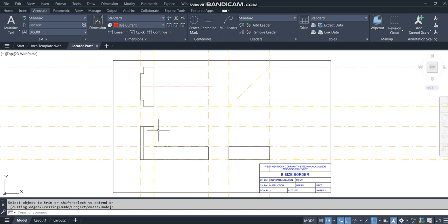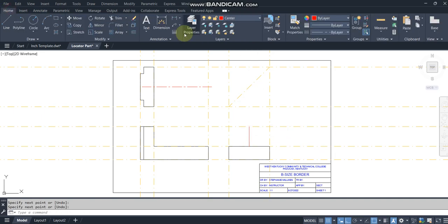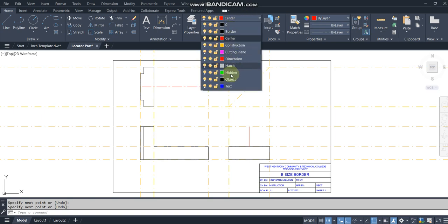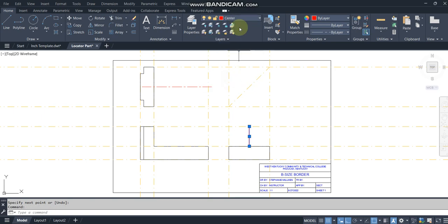In addition, part of that shape goes straight up from this side and then goes at an angle. But in the very middle of it, it's an inch separation. So in the middle of this part, using my object snaps here, making sure I put things on the right layer, I'm going to offset that 1/2 inch each direction.